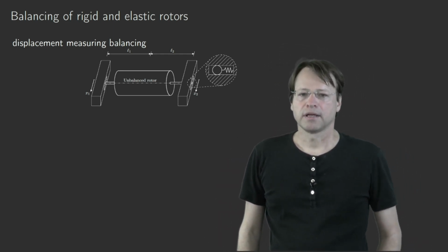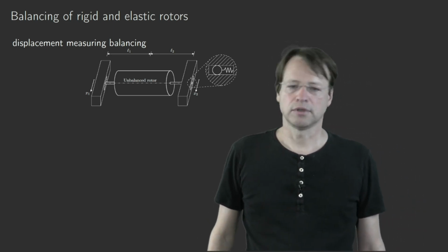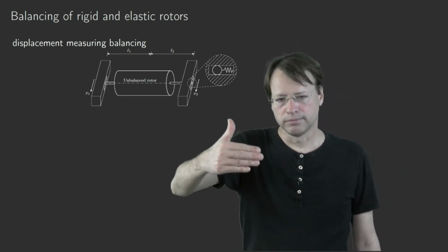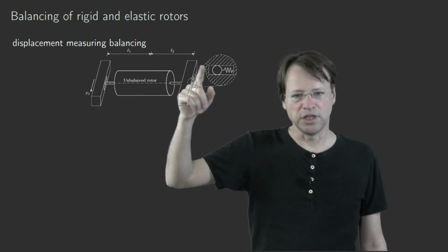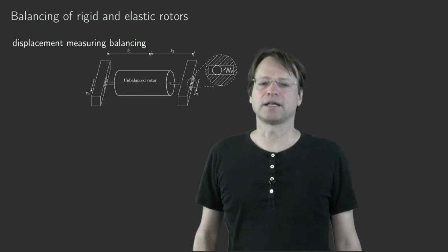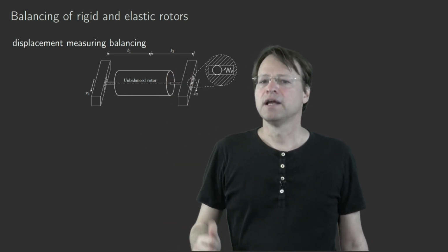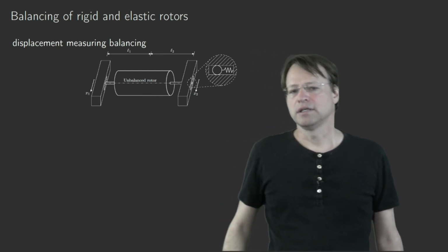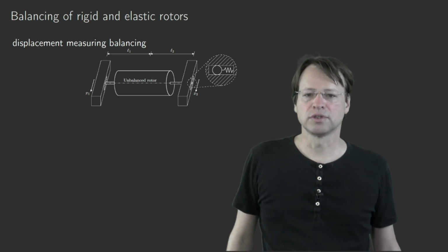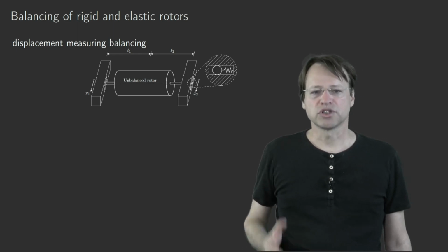So this is now a system that has 2 degrees of freedom. There's, of course, a third one, the rotational degree of freedom, but there is one degree of freedom that is related to each motion on the left and on the right hand side. I could say they act independently, but I could also represent them by one rotation around the vertical axis here and one linear displacement. So it's a 2 degree of freedom system if we consider that rotor in stationary state, and the derivation of the equations of motion is quite involved.